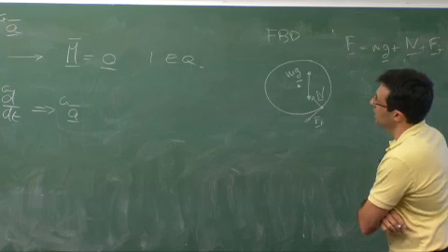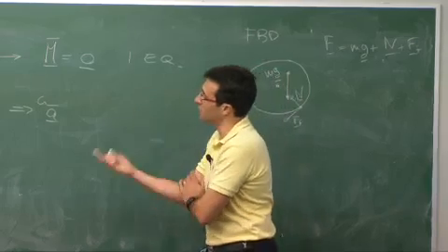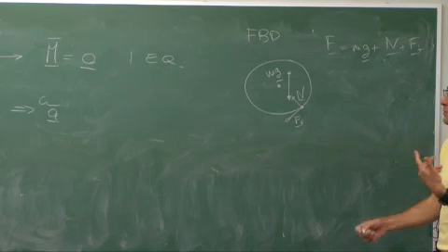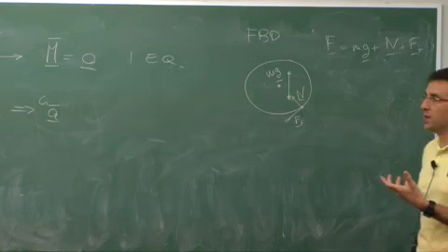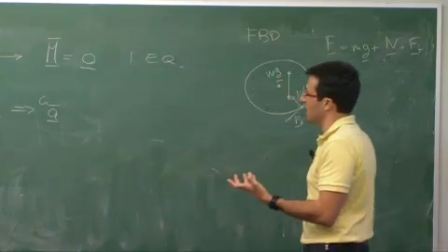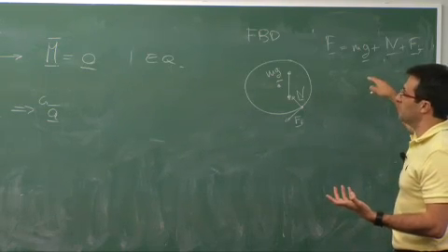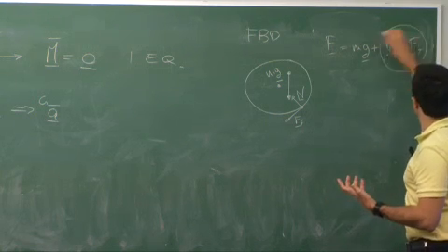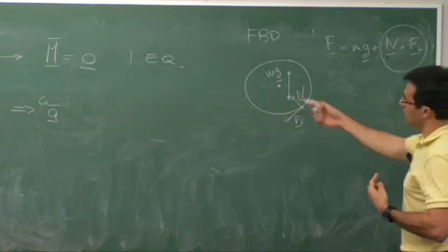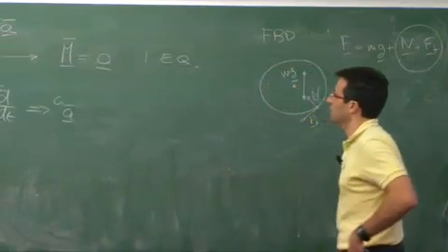And so that's your F, acceleration of center of mass, you figure it out. And so how many equations do you get from that one? So from 1, how many equations do I get? It is time that we start thinking about what we get from the laws that we have, how many equations we get, if they are enough, if they are giving me what I need, if I can eliminate things that are unknown, because that's really the point to getting equations of motion. You don't want to be stuck with unknown forces. I don't know those two. I don't necessarily care about those two, but if I'm using Euler's method, I mean Euler's laws for rigid body, I need to deal with them somehow.